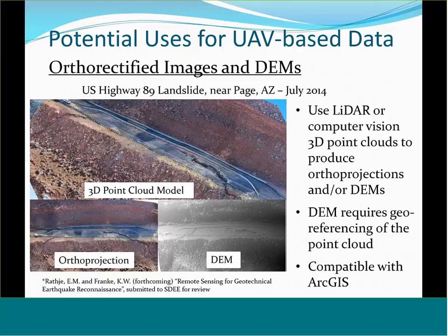With these models that we develop from the digital imagery, we can create a variety of different models. We'll talk about 3D point cloud models shortly, but we can also obtain, as you can see in the bottom left, an ortho projection photo. From those, we can import them into any standard geographic information system like ArcGIS and develop digital elevation models and perform some change detection or try to measure deformations that way.